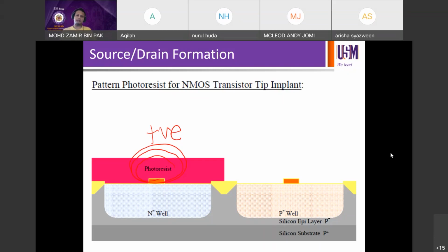Remember when you run the CED in lithography, you have to spin coat semua. Mana boleh spin coat tempat tertentu kan? You have to spin coat the whole thing. But then what differentiates your features will be during the exposure step. So in this case, since the resist is positive, the exposed areas will be soluble and eventually removed, and hence not on this picture.